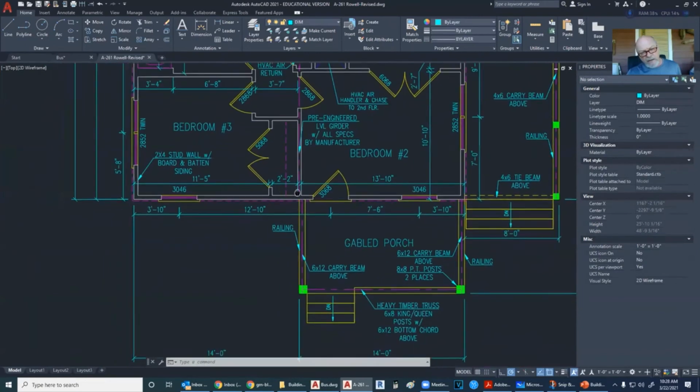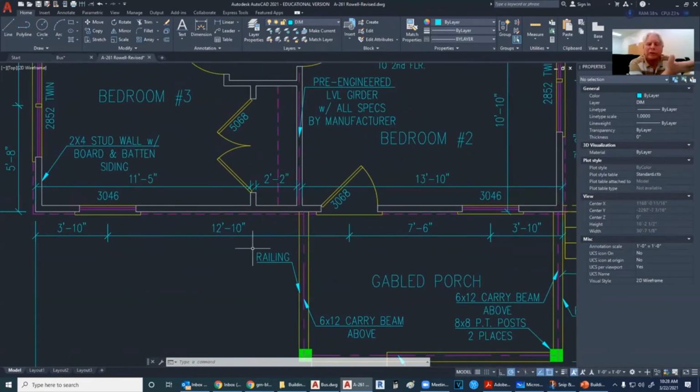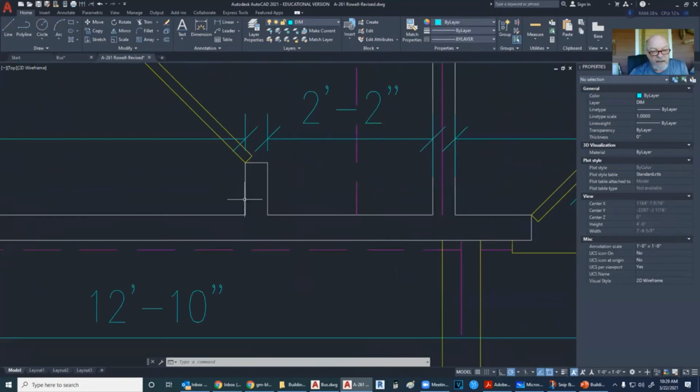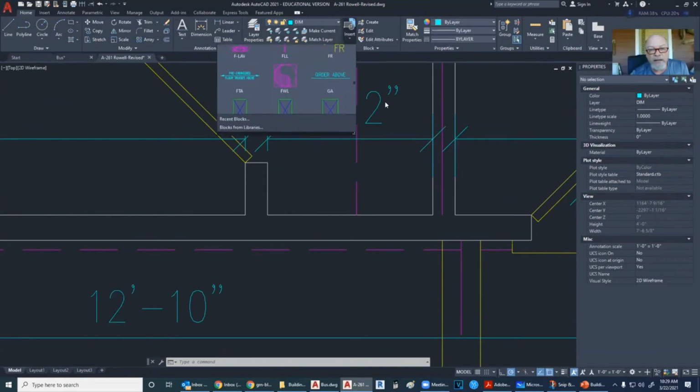How's it not going to come out right? Well, we're calculating the finish, which is the 1/2-inch pieces of drywall, which makes it 4 1/2. Well, if you dimensioned it on a 4 1/2 wall and the framer went by the face to face, it'd be wrong. You've got to dimension to the center to place the stud where it actually needs to go, because then you've got the 1/2 inch on either side. Well, that's what I'm saying. If this is the stud, is that a 4 1/2 inch or 3 1/2? That's 3 1/2.